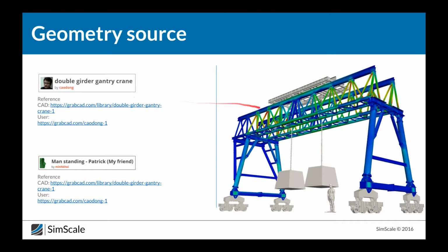He created this geometry in AutoCAD, and then I've imported this into SolidWorks to do the work. So it doesn't need to be a native SolidWorks file. In fact, in most cases, that would be typical to get the file in a format that's just the plain geometry and no history with it.